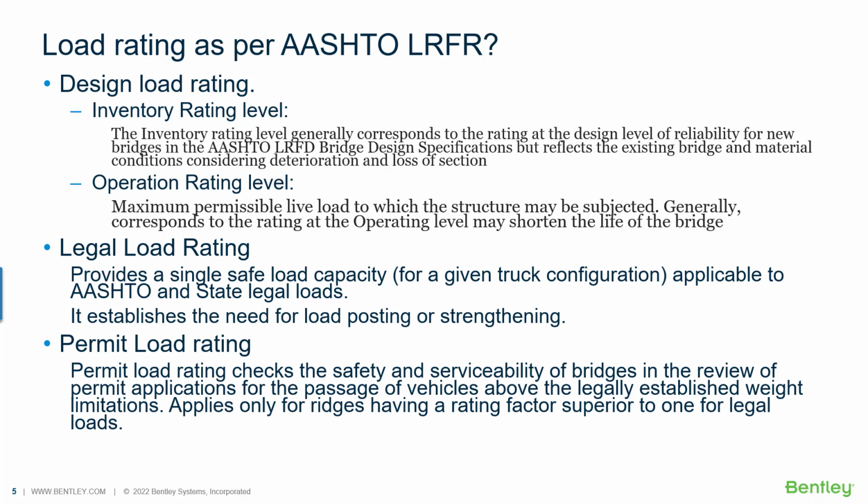bridge. And finally, the permit load rating checks the safety and serviceability of the bridge in the review of permit applications for the passage of vehicles above the legally established weight limitation. It applies only to bridges having a rating factor superior to 1 for legal loads, because if the bridge cannot carry legal loads, we clearly understand that it will not be able to carry overload live loads.